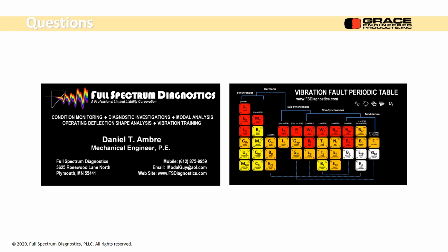So I think Grace actually is they have a triaxial set out there, but they're putting in one of those triaxials as a much higher frequency range. And if you filter that signal, you can see minute impacts of the bearing frequencies as they start to fail. So I think your question has already been thought of, and people are putting an answer in place right now.